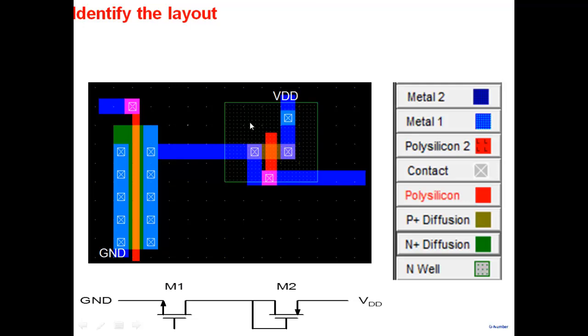And it's for that reason that you see here, they've made contacts distributed all over. So current comes in, and then it can go here, and then these are all low resistivity regions. Current can easily go wherever it wants. And the whole region would be of one single potential here, and this whole region is one single potential. So the general rule is put as many contacts as can be accommodated in your layout. In this case, note that 5 contacts are possible, so they put 5 contacts.